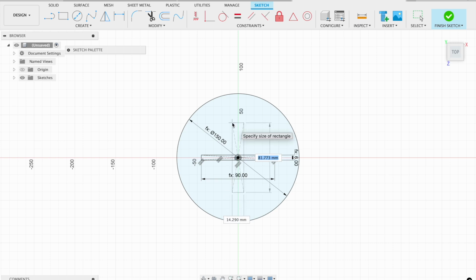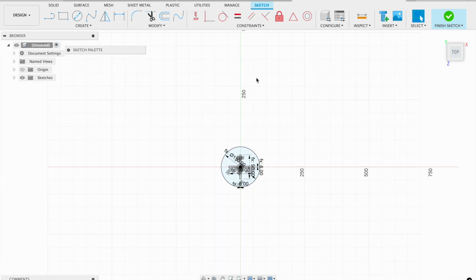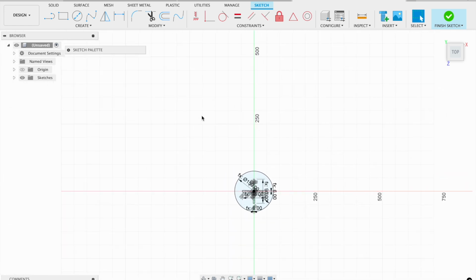And again, on one of the dimensions, it's going to be thick times 15 to give me 90 millimeters. And the other one's going to be thick, which is 6 millimeters. Sorry, 90 millimeters and 6 millimeters. There we go. Now I'm going to start to draw the bottom of the stool.